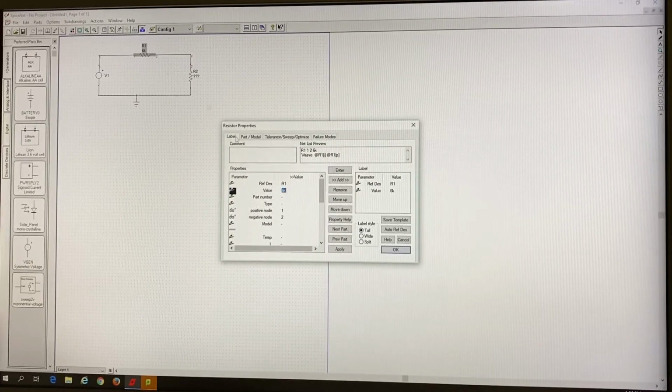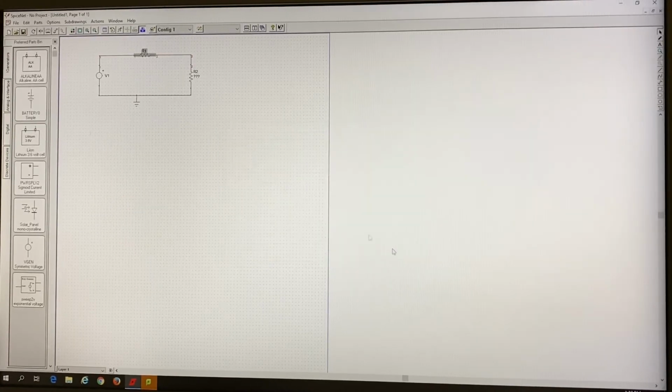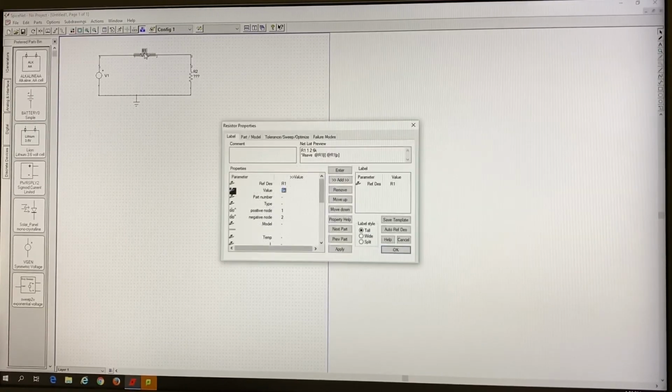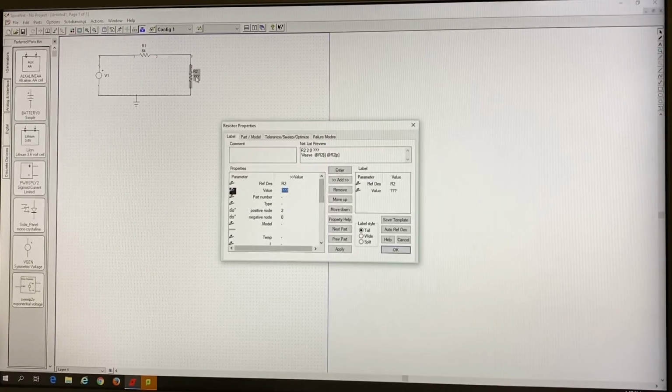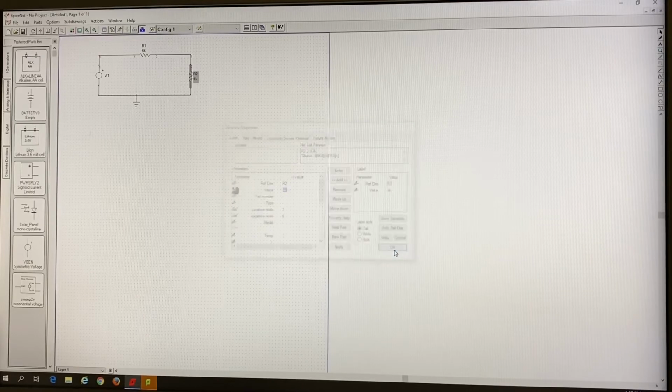So sometimes you might face a problem where you don't see the number or the value of the resistor being displayed. That will mean this one, because you have an option to remove this. See what happens. See, my 6K is no longer showing. So if you want it to show on your circuit, always click on the value and say add. It adds it, then you say okay, now it adds the value. So you do this for all the components. On this one, I'm just going to have it as 4K for now, which means 4,000 ohms, right? Then I just say okay.